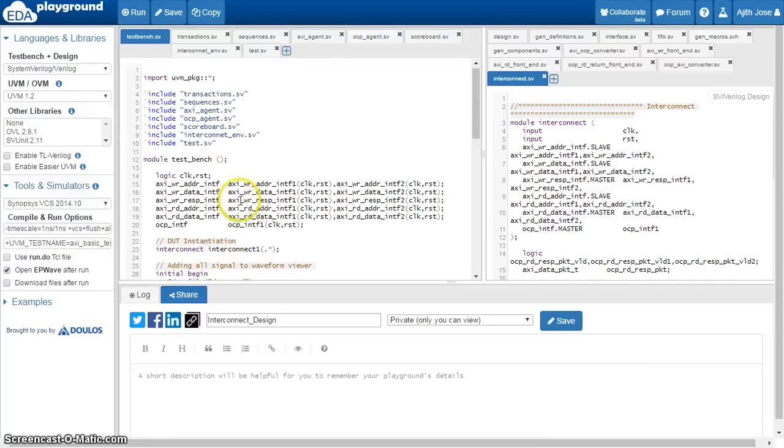When you start your design, you can write a simple test bench to drive transactions directly into these two interfaces one by one. Write a few transactions into the interface and see interactively whether these are coming correctly in different modules. Now I will run the simulation.